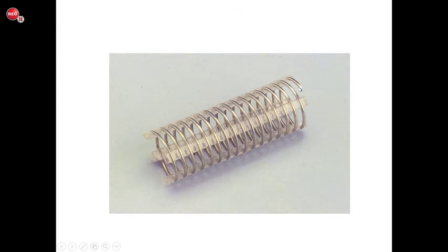This is just an example of a type of coil that uses a heavy wire, and you can see that there's no insulation on this wire. This is what you might find inside of a variac, and so it has few turns of heavy gauge wire to handle high current, and they're separated by this strip here. You can see this is an insulation material. It keeps all of the turns of the coil separate from one another.